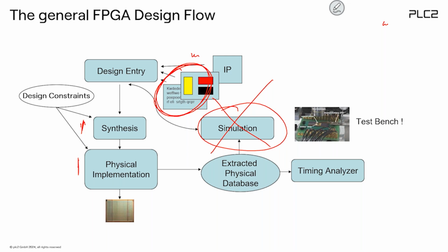It happened a few years back: we got a very nice tool inside the Vivado environment, the CDC checker. The CDC checker will tell you that you do have a problem here, and then we have to analyze the problem and find the proper solution for it. That's the idea of where we are in our general FPGA design flow.